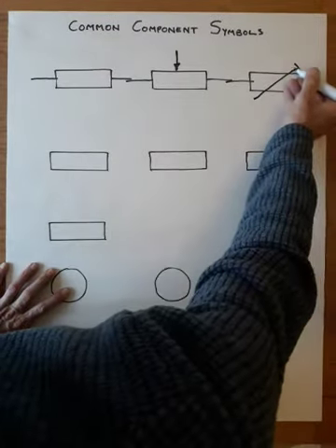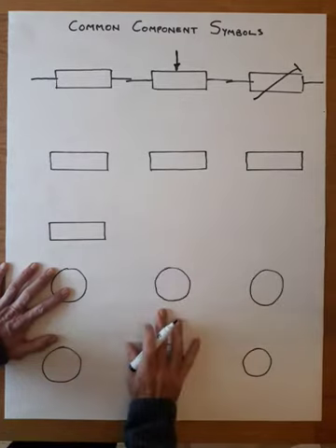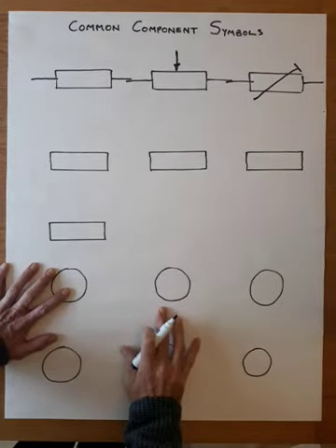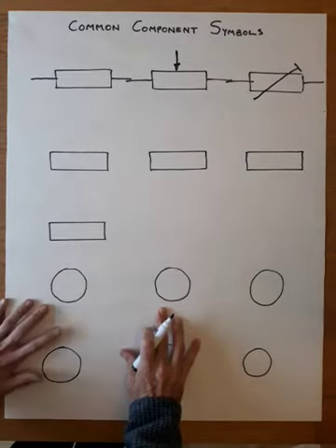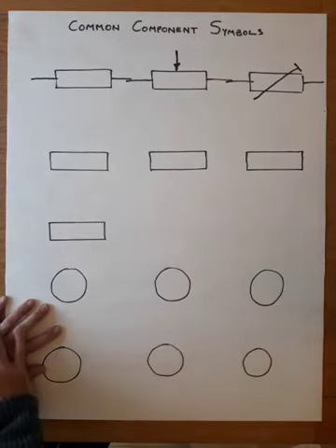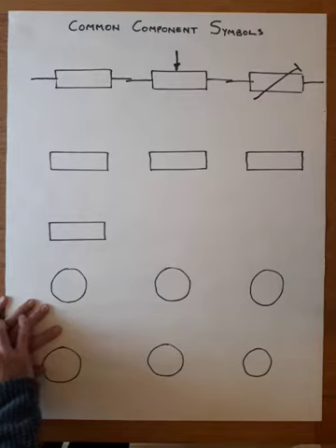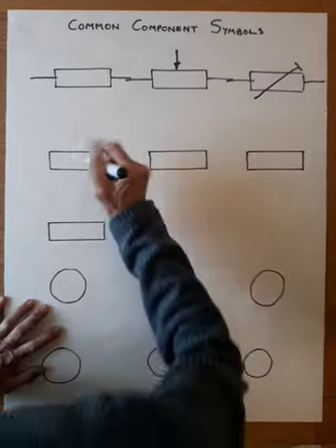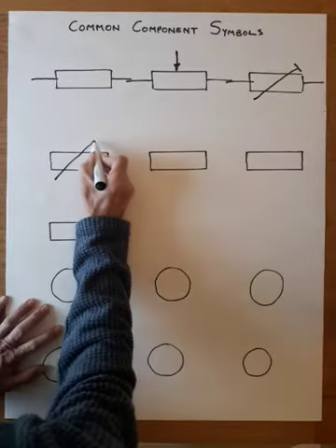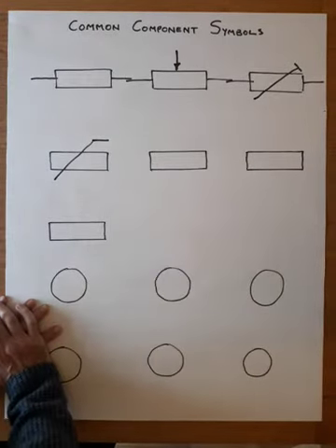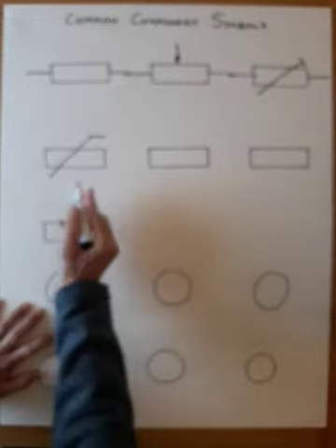so here's standard resistor, diagonal line through it with a flat top. And that means it's a preset resistor. Those are components which you will normally never see unless you take the back off perhaps a television, hi-fi, or some other piece of equipment, and they're usually adjusted in factory before the equipment leaves. The next one, again a line through it with a different flat top, so this is at an angle. This is a thermistor.